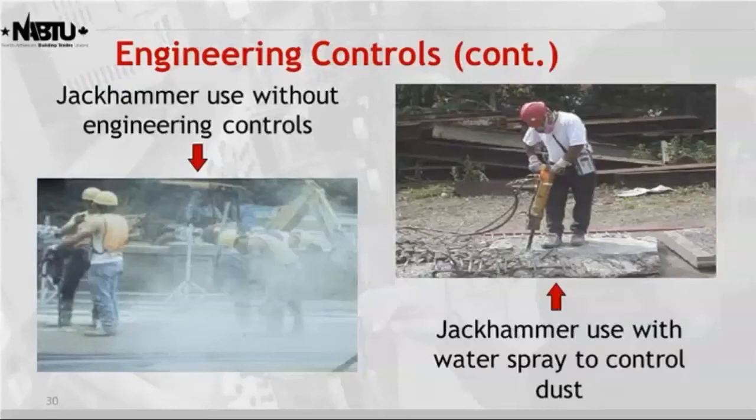All right, here's another picture of a jackhammer being utilized. Just to reiterate, the silica standard is not only to protect the worker involved in the task, but the other fellow workers on the site. Look at the picture on the left, how those other 2 workers standing there are exposed. The one on the right is a very good picture of just using water spray. Notice there's virtually no dust. So water is one of the most common methods for engineering controls.